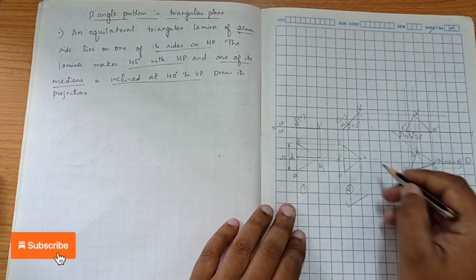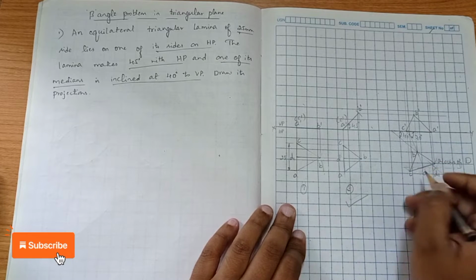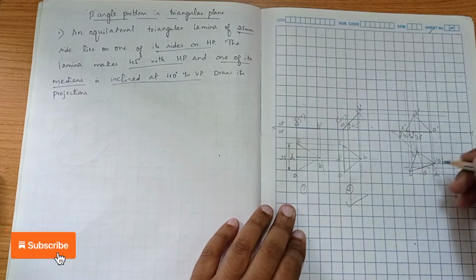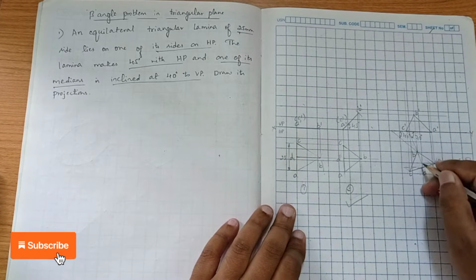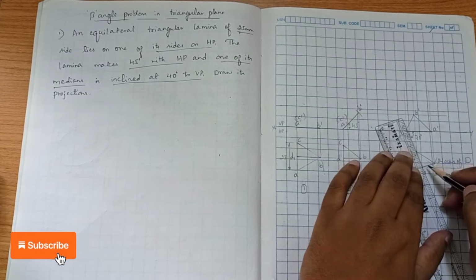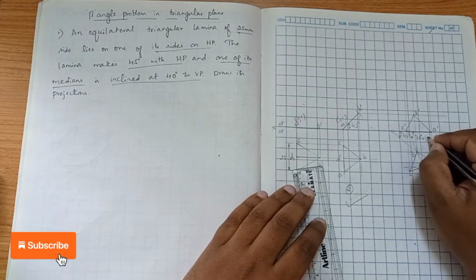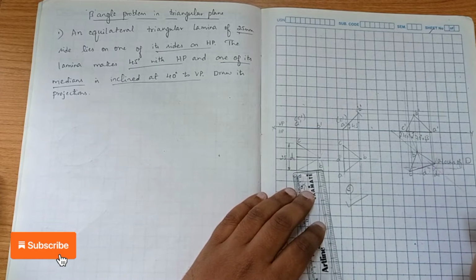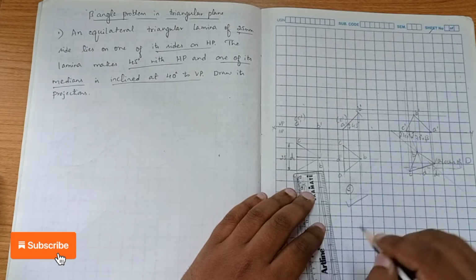After that we measure again from B to D, and we cut the arc on this locus line. So there is a locus line here, right? On this locus line we cut the arc. After cutting the arc, we join BD, and then we extend this BD line using a scale till it touches the XY line. After that we find out the angle. This is your beta angle. Beta angle 70 degree, around 71 degree you have to get. If it is 1 or 2 degree variation, there is no problem. Then by the same procedure, extending from C, from B, from BA, we'll get the final diagram.